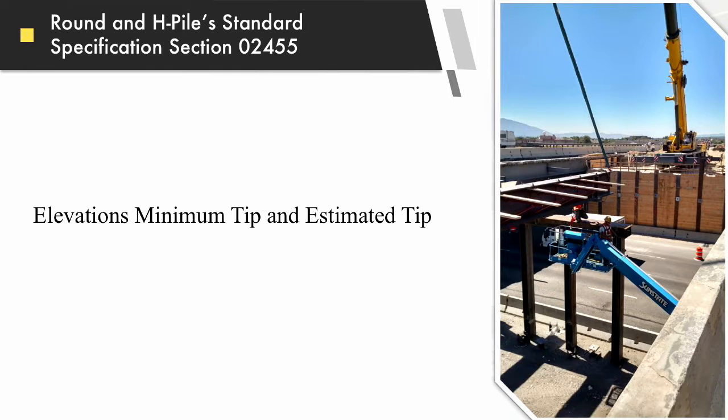But just like with this one, those H piles, if you went off of minimum tip and you had your elevation down at the bottom and you didn't calculate that out to cutoff, and the contractor's got people that are calculating that too, but just so that you know how many feet into the ground your minimum tip is supposed to be.